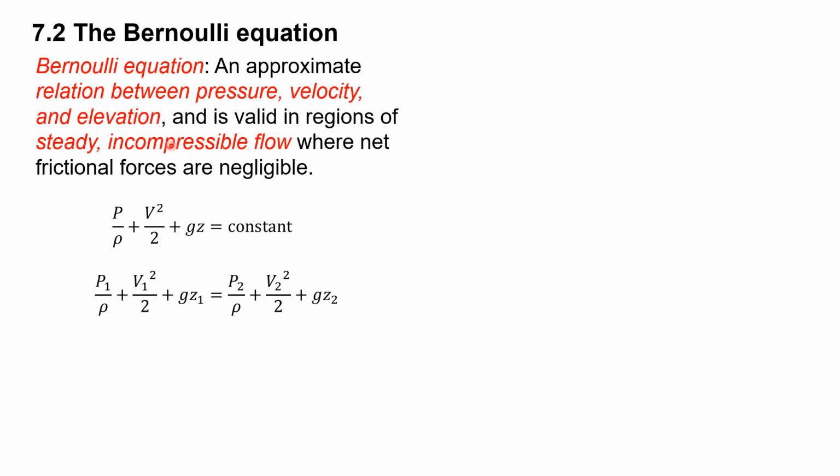One important thing about Bernoulli's equation is that it is valid in a region of steady incompressible flow where net frictional forces are negligible. Meaning this Bernoulli's equation cannot be used in all situations, because if there's a lot of friction, a lot of vorticity, a lot of changes, then you cannot apply it because it will keep on changing. You can apply Bernoulli's equation, but you need to take point by point.